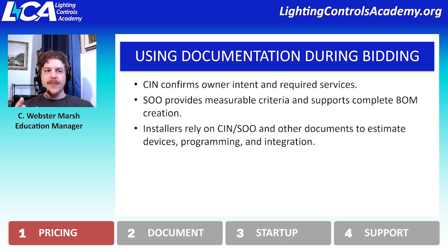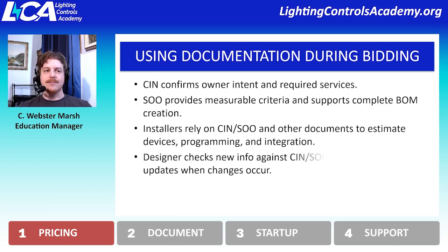Whereas if they just work off the sequence, their quote might actually be more accurate at the end of the day. And additionally, they will work with the manufacturer's rep, as I've mentioned, to come up with the cost of programming and services that will have to come with that system. And so through that discussion of, okay, here's what the sequence of operations is asking for, the manufacturer's rep can then look and see, okay, this is what we're going to have to do for services, this is how much time it's going to take, and they can provide a pretty accurate quote to how much time it's going to require to start up that system.